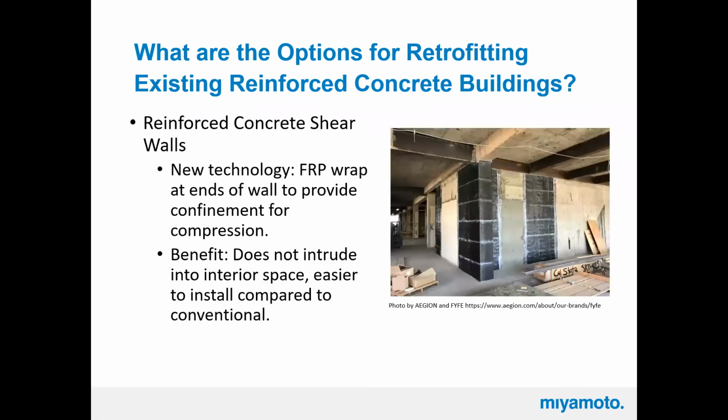Again, more concrete shear walls with FRP. This says it's providing confinement for compression. Could well be if it's properly anchored and detailed. And again, the benefit is it doesn't really take up much space. So that's sometimes a make-or-break deal for your project. So be aware of that.